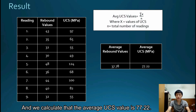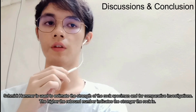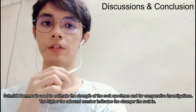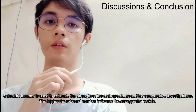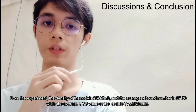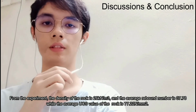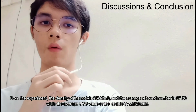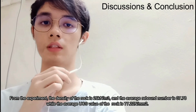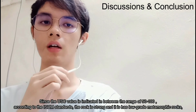The Schmidt hammer is used to estimate the strength of the rock specimen and for comparative investigation. The higher the rebound number, the stronger the rock is. From the experiment, the density of the rock is 26 kN per meter cubed and the average rebound number is 37.78, while the average UCS value of the rock is 77.22 Newton per millimeter square.